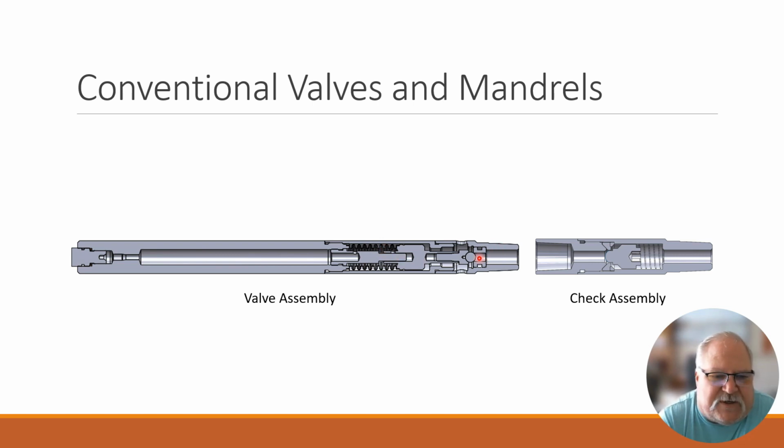Then you have pressure on the valve, the pressure that's pushing, that can kind of come through your check valve. It can be pushing up on the bottom side if it's open, so there is some impact on there. Most of the valves we use are not, this is showing a spring in there that's actually forcing the seat closed, but usually it's just a differential check. So if there's any kind of backflow pressure, it'll push it up and set it and keep it closed. It's not spring loaded, but we can do springs. But that's basically what a conventional valve looks like.